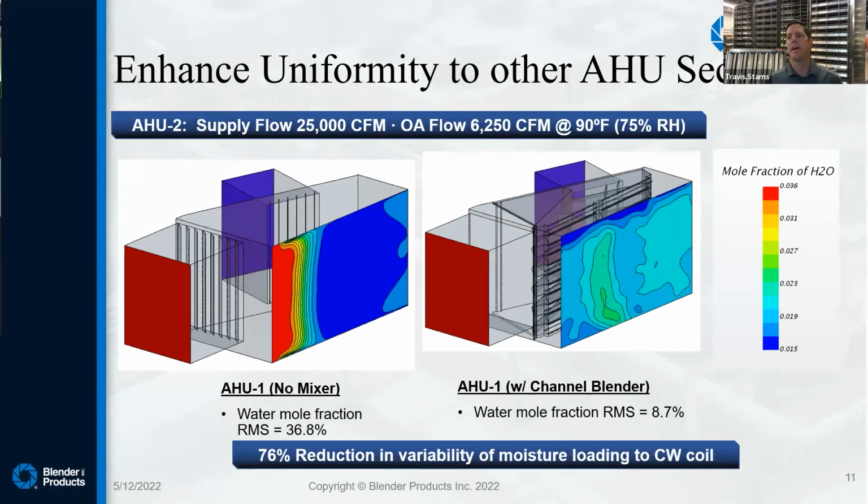And so to do that during hot summer months, especially on side entry units, if we could reduce the variability of moisture or water going to that coil, they would have better operation. So what we've learned is that if we can raise that inlet suction temperature to the chiller by 1 degree Fahrenheit, that adds 3% efficiency gain to that chiller.